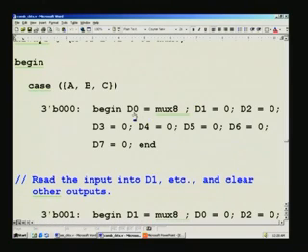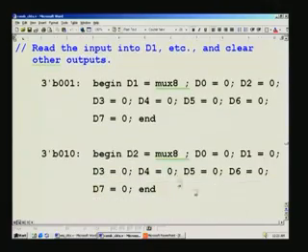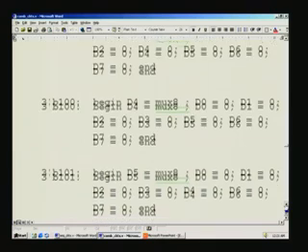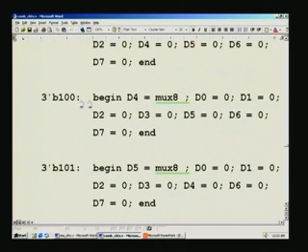And here, only this one is applicable. So, what happens to the other outputs? You have to force them to 0. If you do not, you may land up in a problem later on, because it might have come from an earlier state with 1, so it latches on to that condition if you do not mention it. This also we have seen while dealing with RTL coding guidelines. And similarly for other cases, all the 8 cases are considered here, and in each case you see that mux 8 is assigned to the corresponding output. This 4 corresponds to this 4, although it need not necessarily be.